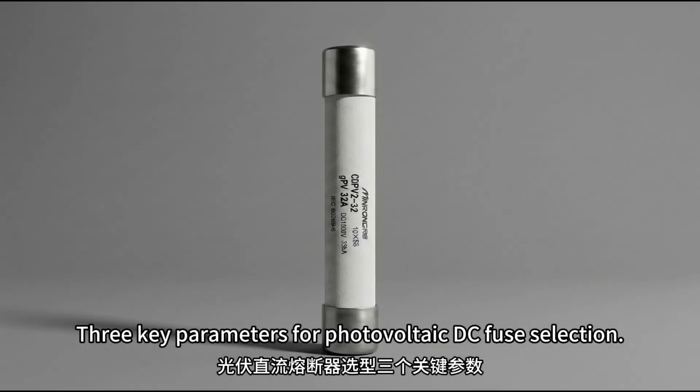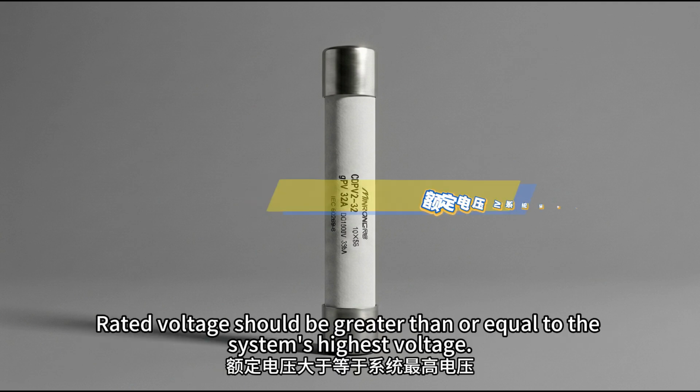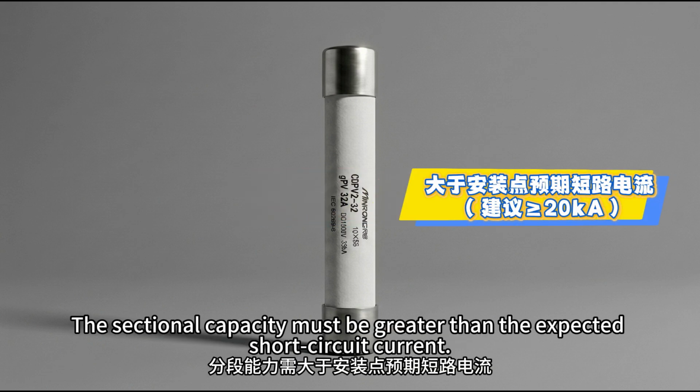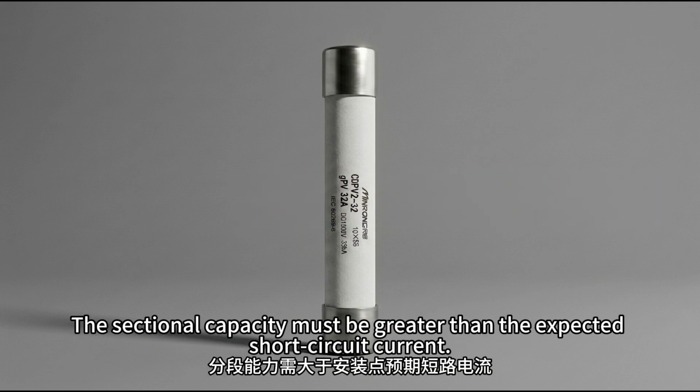3 key parameters for photovoltaic DC fuse selection. Rated voltage should be greater than or equal to the system's highest voltage. The protection category must be GPV. The breaking capacity must be greater than the expected short circuit current.